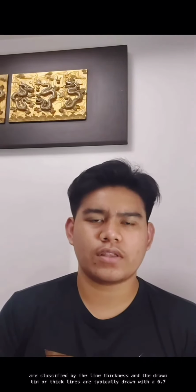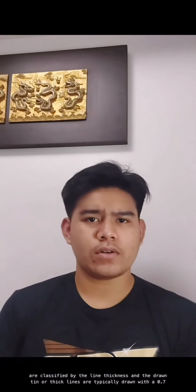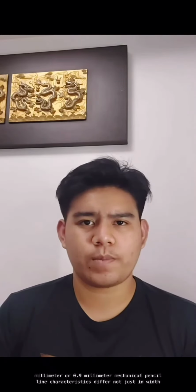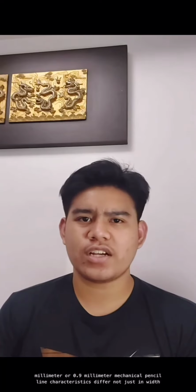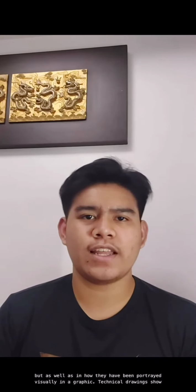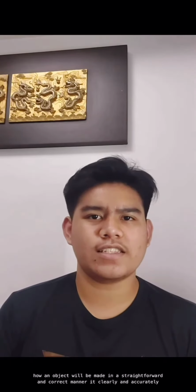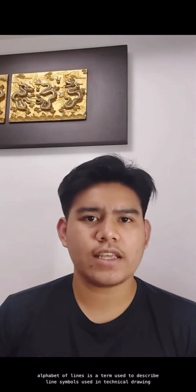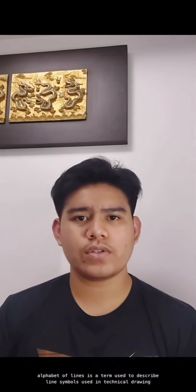and drawn thin or thick. Thick lines are typically drawn with a 0.7 mm or 0.9 mm mechanical pencil. Line characteristics differ not just in width, but also in how they are portrayed visually in a graphic. Technical drawings show how an object will be made in a straightforward and correct manner. It clearly and accurately depicts and explains the information necessary to develop or produce a product. Alphabet of lines is a term used to describe line symbols used in technical drawing.